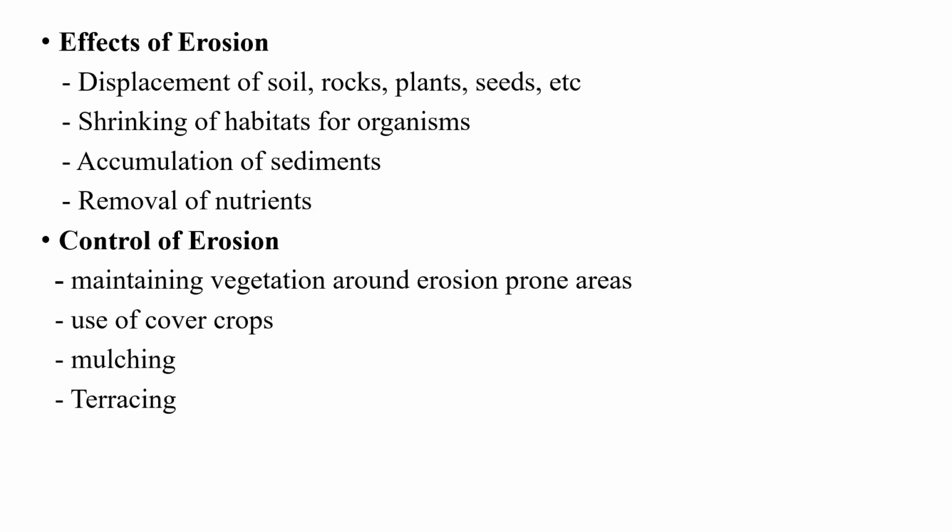And when it falls on the leaf surface, the water will gently move to the ground, and the force has been reduced. As the force has been reduced, definitely the speed at which the runoff will move will be reduced, because even the movement will also be reduced by the plants, that is, by the stem and the roots that are inside the soil.